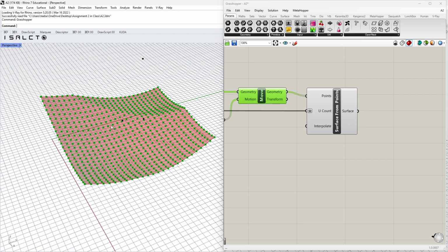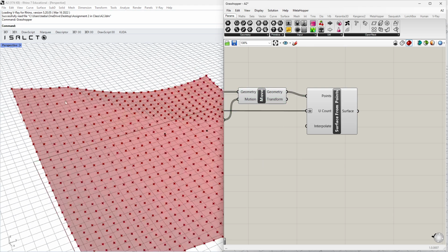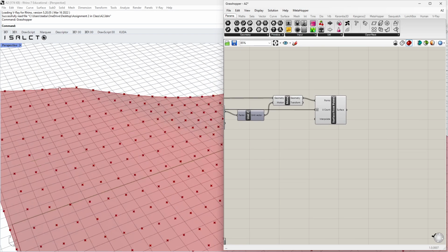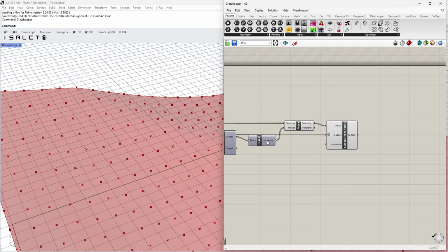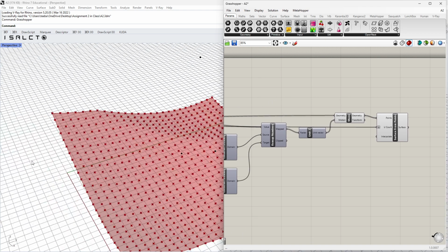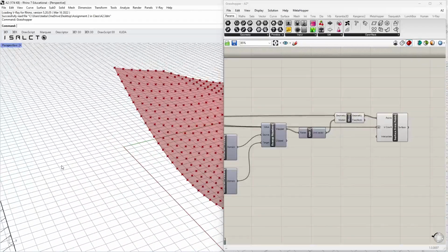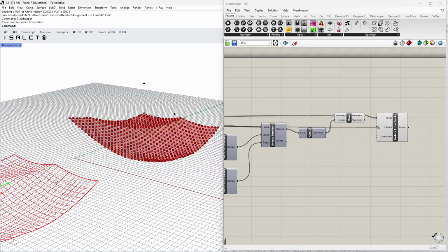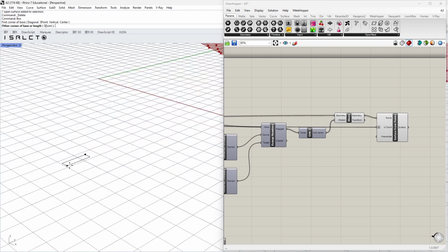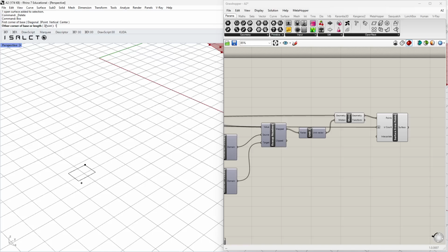So for example, you can do a very simple thing: if we want to make a sphere here, we can do that, and we can also control the scale with this distance, right? But I'm not going to do the sphere, I'm going to do the cube. So just follow me. Let's go to Rhino and make a cube. Use box. I'm going to make a one unit cube. I just click anywhere on the canvas and type 1, 1, and 1. So that will be a cube.